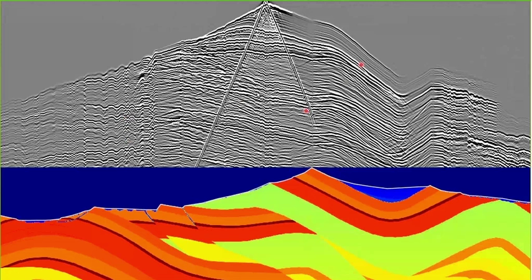Over on the right, you see this huge time delay due to this thick weathering pocket, and then, as I mentioned before, on the right here, where we have a slower velocity coming up to the near surface, we see a massive delay in our first arrival times as expected.